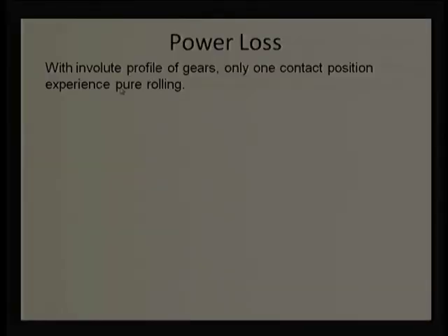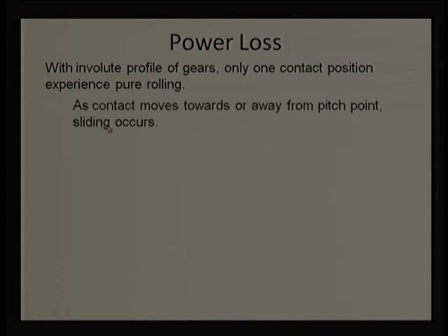I am just repeating this slide with a few observations from the previous lecture, where we say that with the involute profile of the gears, only one contact position experiences pure rolling. Pure rolling happens only at the one point. Now, as the contact moves towards or away from the pitch point, sliding is going to occur. There is a trend here: sliding will continuously increase as we move away from the pitch point.